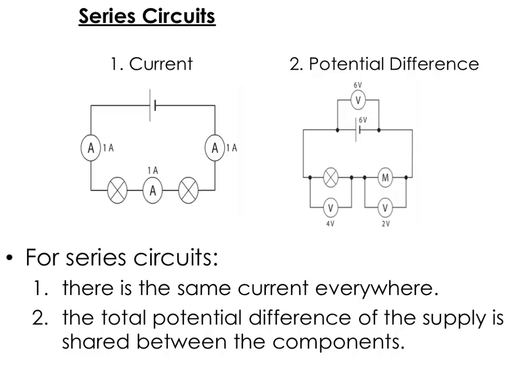If we look at a series circuit for potential difference now, again, the current only has one direction to follow, it can only go this way around. The current cannot go through the voltmeter because the voltmeter has extremely high resistance. But the voltmeters have to be connected in parallel so they go across the component you want to measure. The reason for this is so that the voltmeter can determine the difference in energy that the electron has before compared to after it goes through the component.